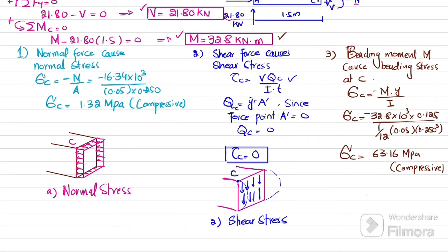And the third case is for the bending stress. So how we will do it: this is its neutral axis, and this is the beam. We know that the above portion was in compression, so I can draw the diagram like this, and the portion below is in tension. I will also show you how it will be in tension and compression. You can see that this will be a straight line. So all these stresses will be in compression, and this will be in tension.